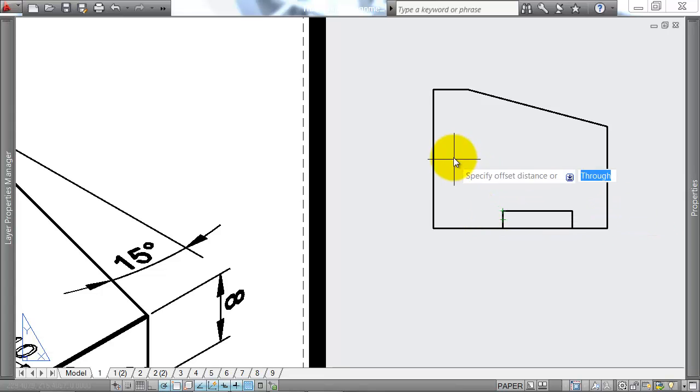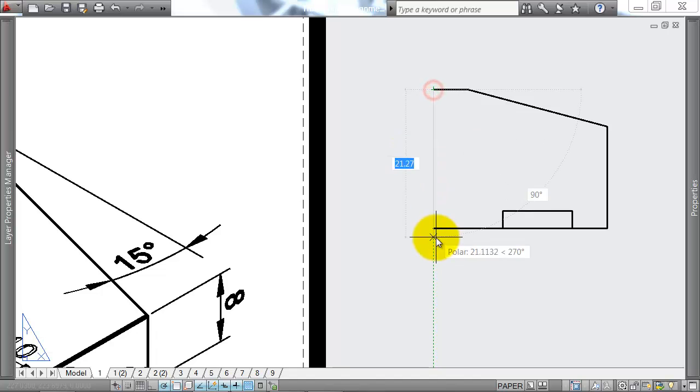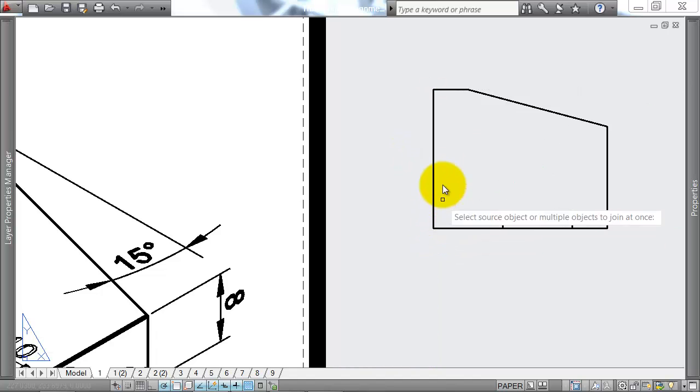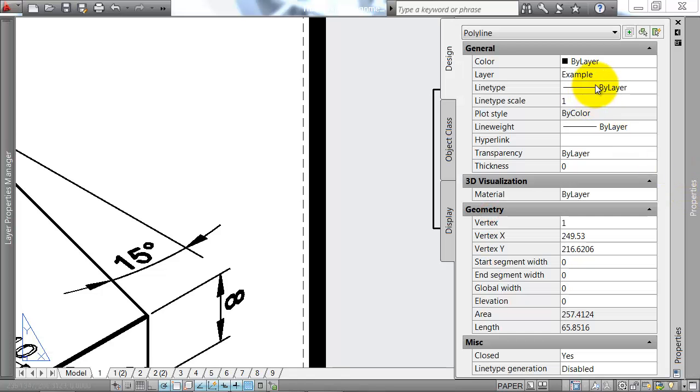Now there's a shortcut that I can use here, only in AutoCAD of course, not on paper. If I use a polyline instead of just a line, and I join this polyline to all of these lines around here, when I use the offset command and set my distance to the distance to offset, I can do all of this in one hit. Drop that in like so. And then I can change this line to be a hidden line.